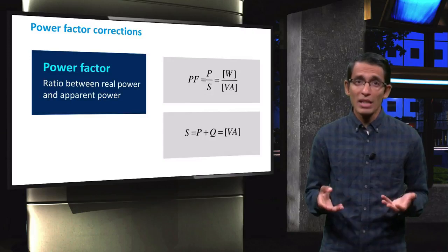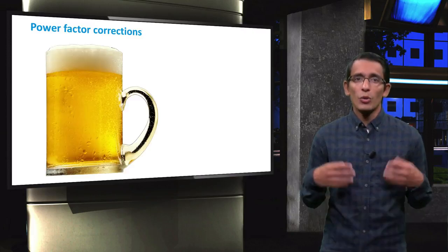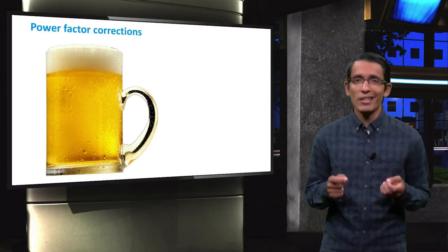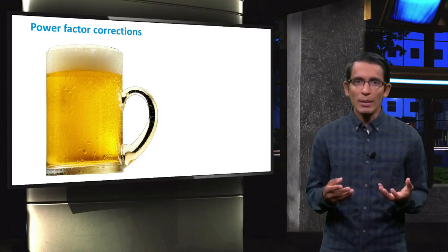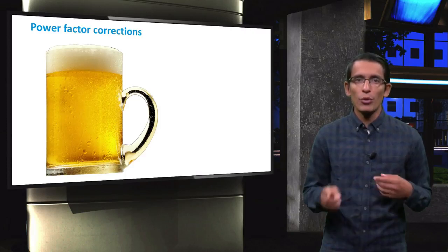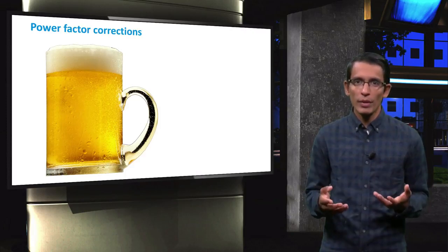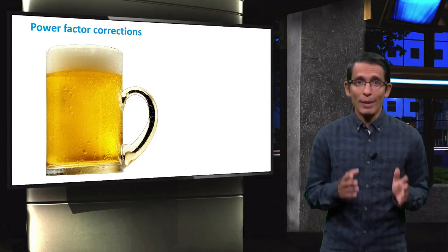But what do I mean by active and reactive power? Well, transmission lines have a certain inductance and capacitance. Due to this unideal impedance, some of the AC power traveling through them is recycled through the lines and never reaches the load. This is known as reactive power.